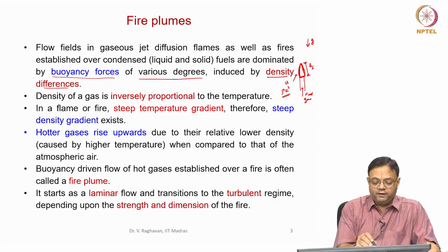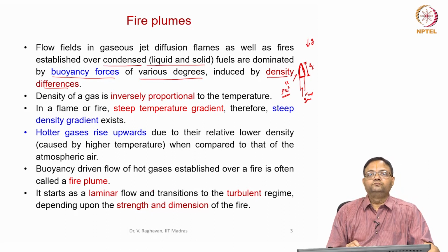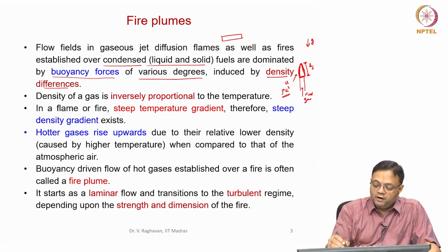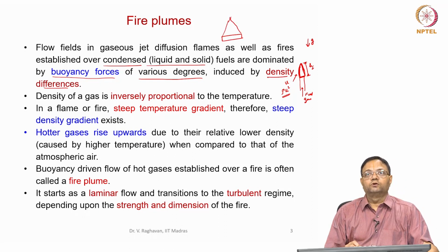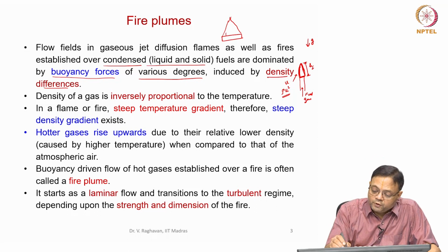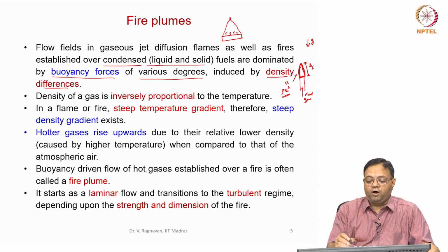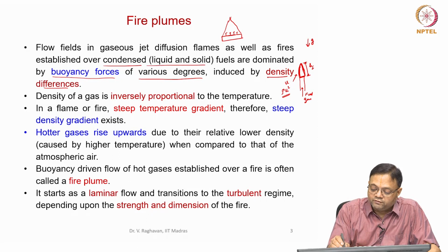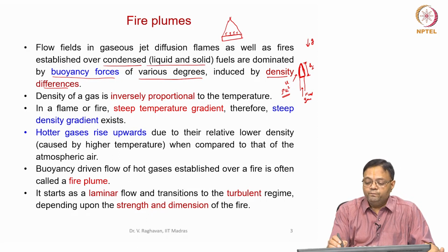But if you take the fire established over condensed fuel, like a solid fuel or a liquid fuel, then you have a condensed fuel surface and a fire is established over this. Now, if you see the fuel vapor in the case of liquid or fuel gases in the case of solid, which are coming out of the condensed fuel surface, they will not have much momentum.